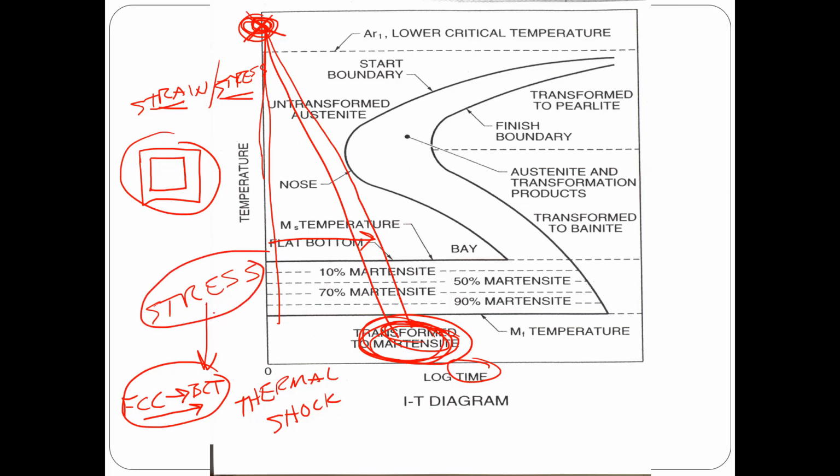And if my total stress exceeds the strength of my material, I have failure. So the more time that I have here, more time for my stress to reduce, the less failures that I have. That's why our critical cooling rate is so important.